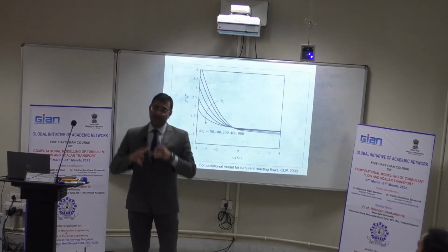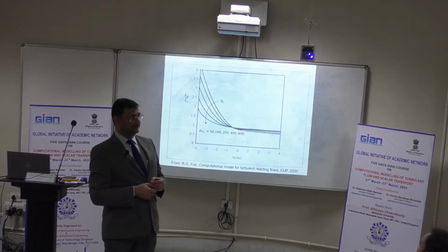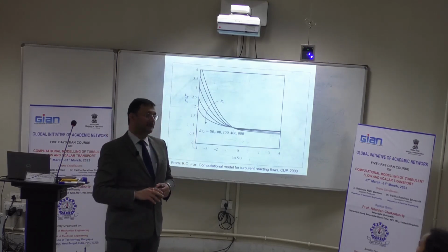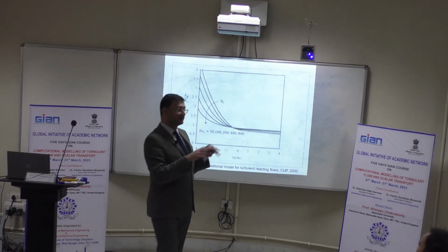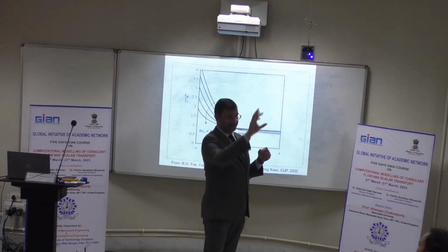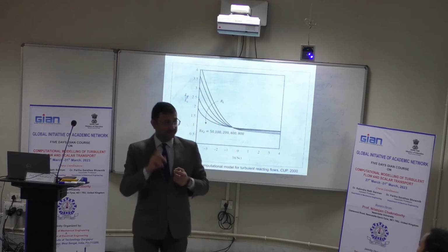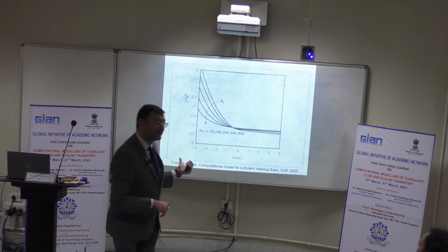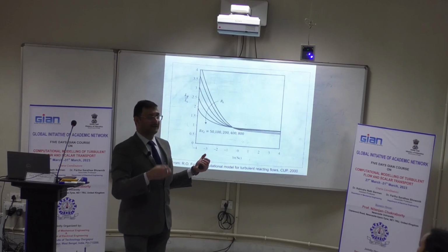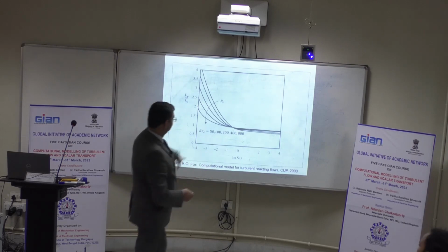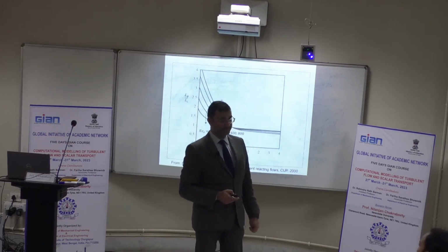Think about that you have a diesel engine cylinder, you have injection of fuel, let's say it has evaporated. Depending upon the injection characteristics and its evaporative properties, you'll have different size blobs to begin with. That integral length scale might be different to begin with, but we are talking about gaseous flows. If we allow it to mix for a couple of eddy turnover times, it will come back to around this range. Okay?